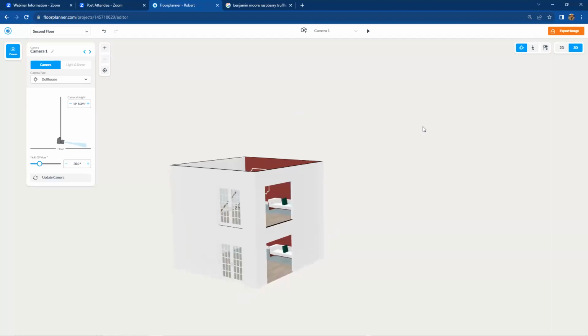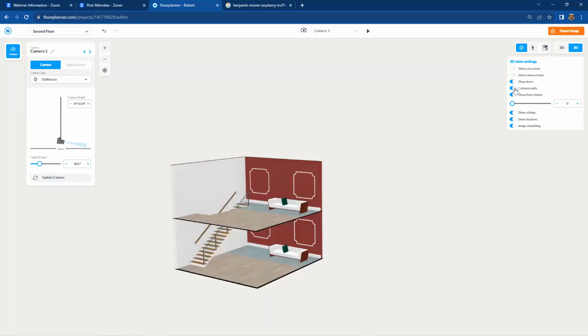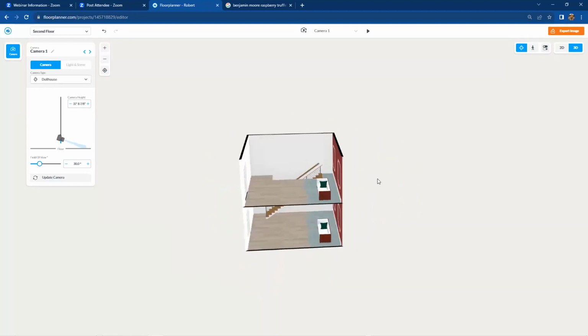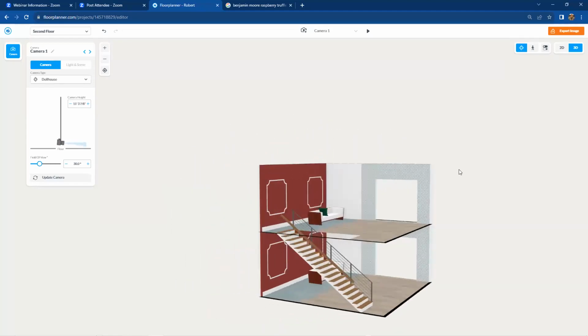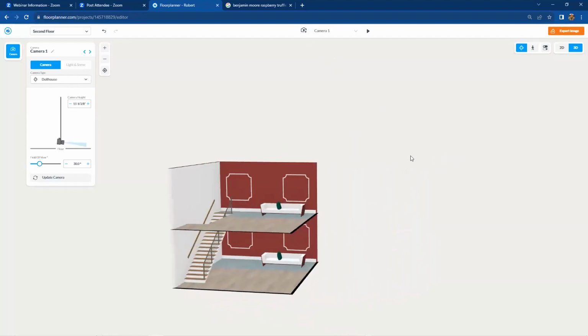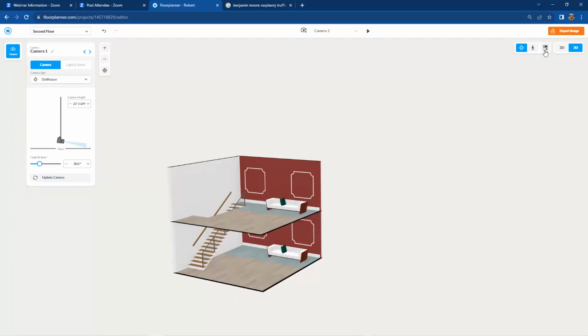And you also have the power in here. You may be aware of this 3D settings tab. There's cutaway walls. Cutaway walls will turn off the exterior walls between your camera and the target point that you're looking at. Again, you can save these with the Camera Plus up here for images and render these for whatever purpose of whatever you're trying to describe. I could go ahead and turn off the cutaway walls.